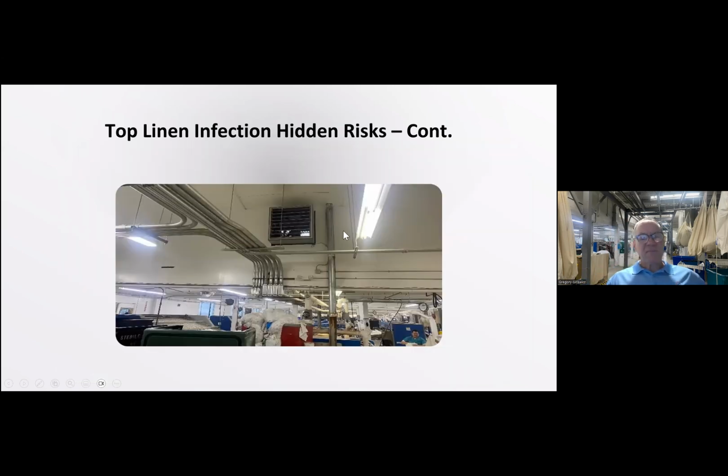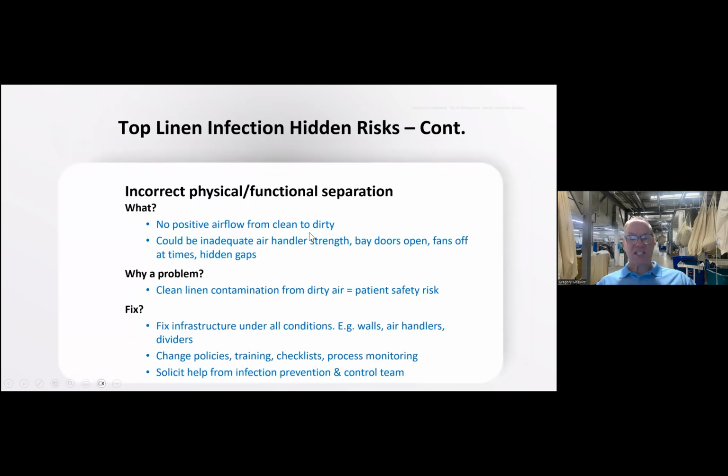Okay, next one. This is pretty obvious. This is an air handler. And on this side is dirty. On this side is clean. So we want to make sure that this air handler is working properly and doing what it's supposed to do, making positive airflow from the clean side to the dirty side.